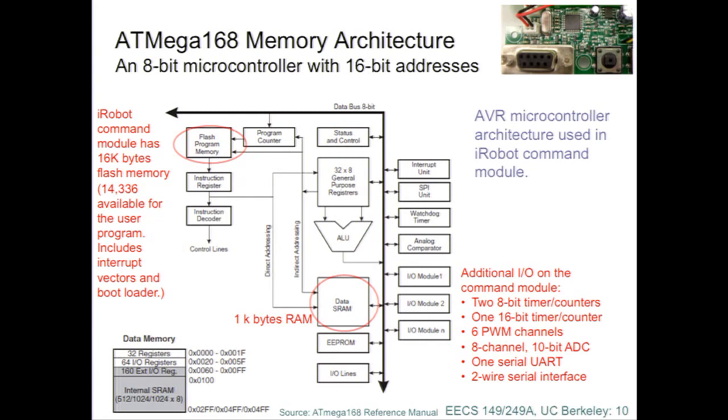So it has 1 kilobyte of RAM right there, and it's static RAM. So the timing of this processor is actually very predictable. That's another thing I like about it. If you look at the assembly code, you can figure out the timing of all of the I/O operations by just counting instructions between the operations. Okay? Can't do that with a lot of other processors, right? But if you need really precise control over timing, these low-end processors are often a better choice than a high-performance, high-end processor because you can really control the timing. Okay?